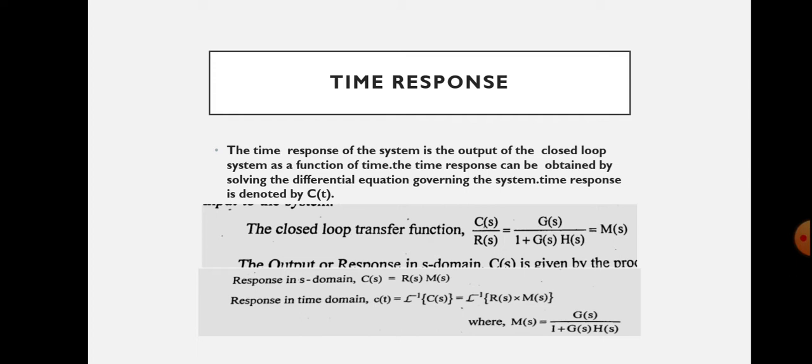and the corresponding response in time domain will be obtained by taking the inverse Laplace transform of C of S. So C of t will be equal to L inverse of C of S, that is equal to L inverse of R of S into M of S. This is the basic terms in the case of time response, that is we are measuring the response based on time.